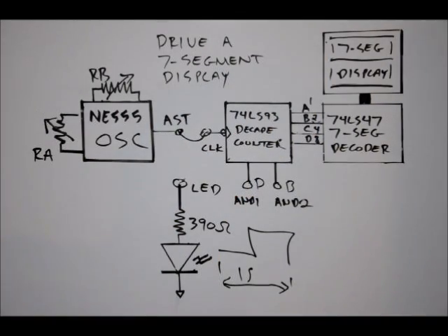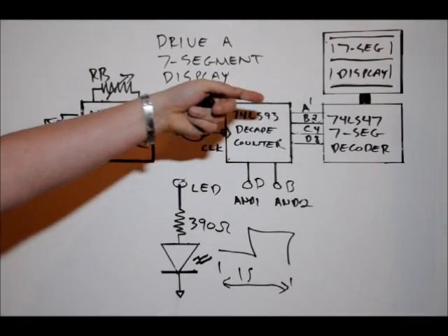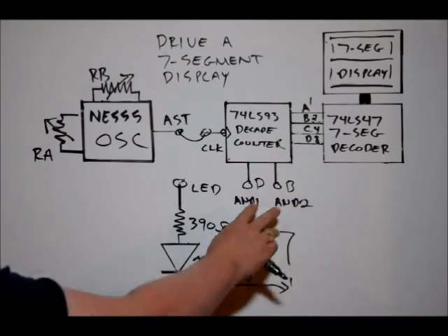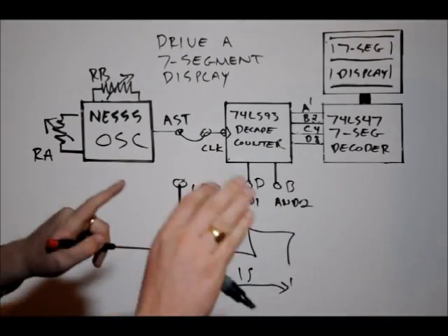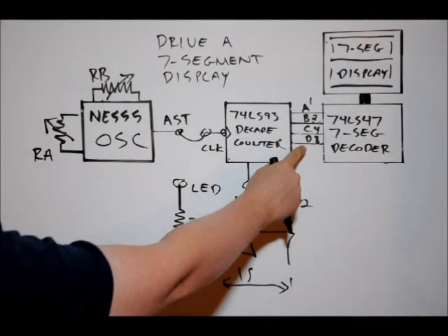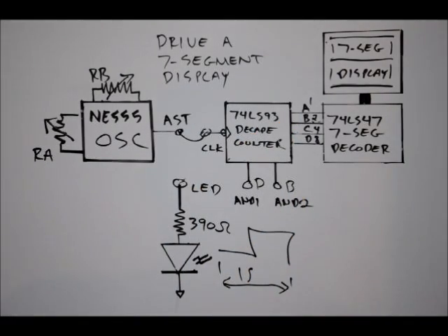So what happens when we get to 10? It's a single display. Well, the 74LS47 decoder offers up some weird characters to the 7-segment display between a binary weight of 10 and 15. They're really kind of ugly. They don't make much sense. I don't like it, so I'm going to have our device reset the instant the logic on these lines is 10, in the case when D and B go high. So the device will count from 0, 1, 2, 3, 4, 5, 6, 7, 8, 9.